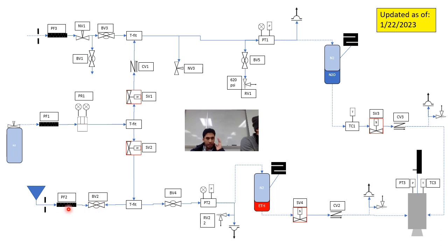So if you were to explain the physics behind this: we first isolate 2 cups of ethanol into a bottle, which is the funnel part of the entire feed system, and then lower the pressure regulator to just above 1 atmosphere. So we have the funnel over here, and the lower pressure regulator, which is this thing.